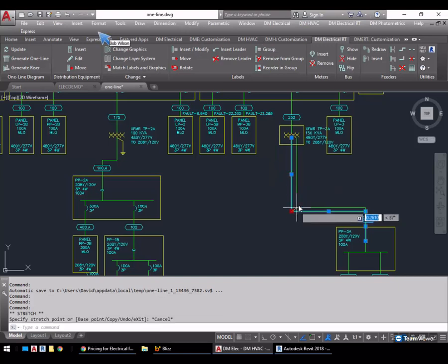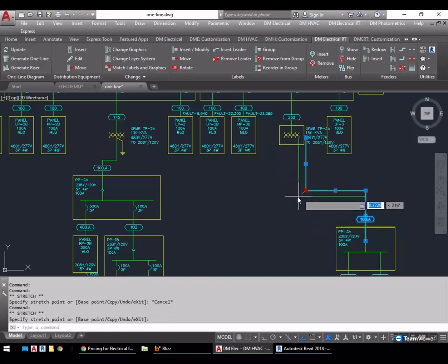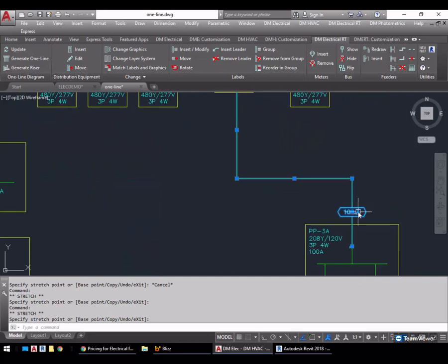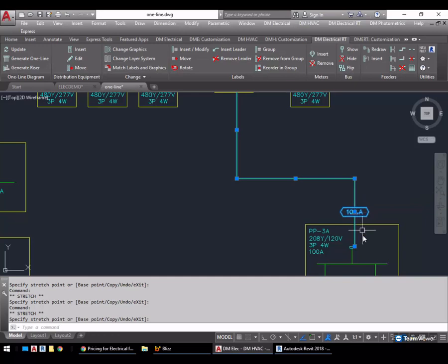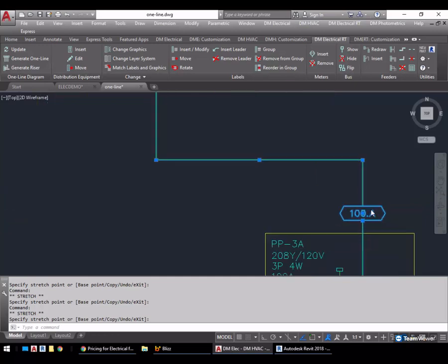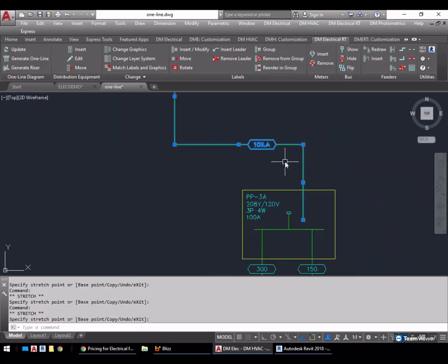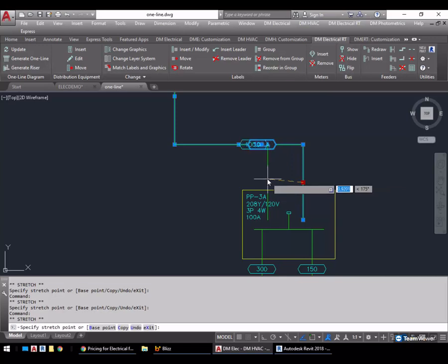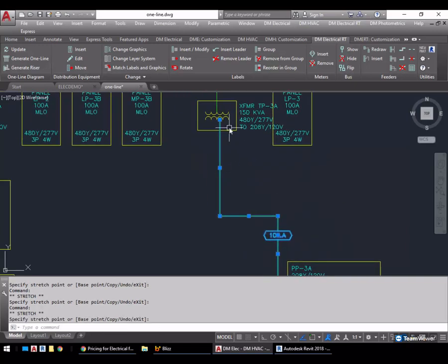If you select one of the corners, it'll move the two edges connected to that corner. So we have those grips there. There's also a grip for the feeder ID. Sometimes it ends up right on top of the other grips, so you have to move things around to get to the right one, but you can move the feeder IDs. If when you're moving the feeder itself, you run into the feeder ID or any of the other graphics, we will move the graphic and do our best to relocate things, but you might need to at that point make adjustments.